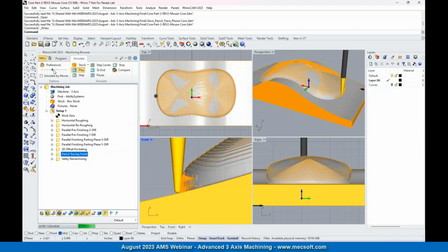So it's working its way down. And you'll see that it's automatically putting the 5-degree taper. And the 1/16 ball is tangent to these two surfaces here and here. Looks like it went all the way through. Let's run that again.